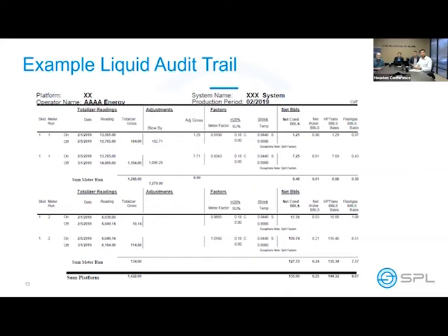You'll notice that those are split on a given day, and that is actually due to the meter factor, where we had a meter factor being determined, and then there was a swap out of that meter. And those meter factors, of course, are directly related to those indicated volumes. So we have to split those indicated volumes at the time of the new meter being installed.